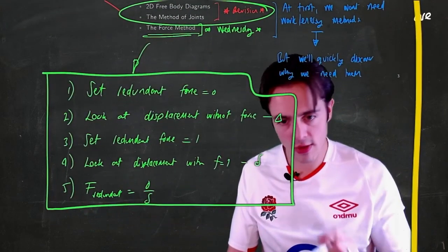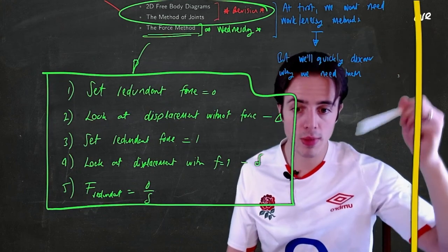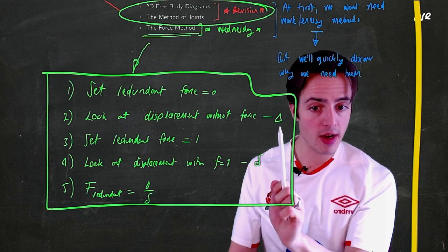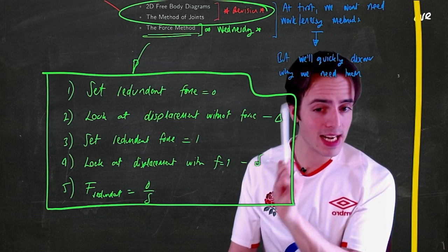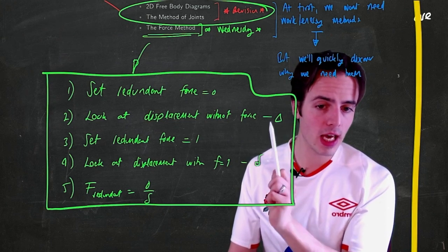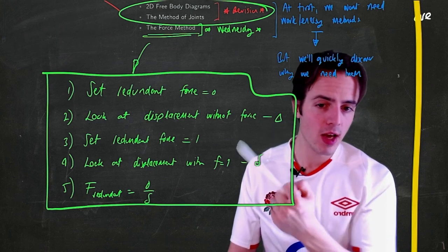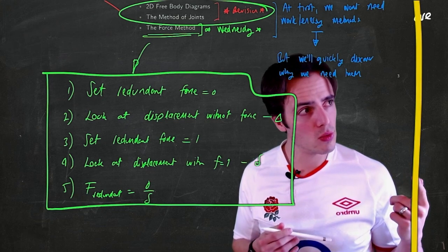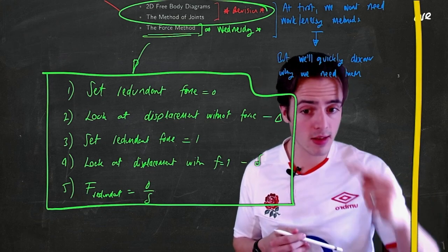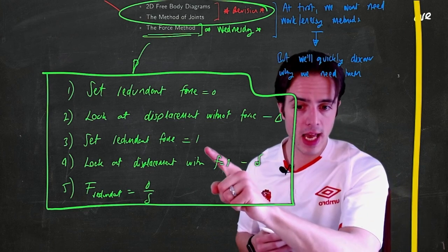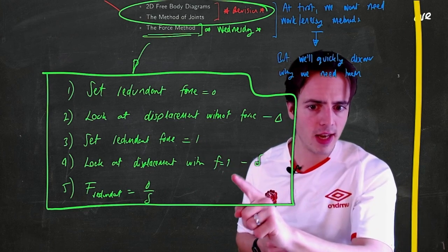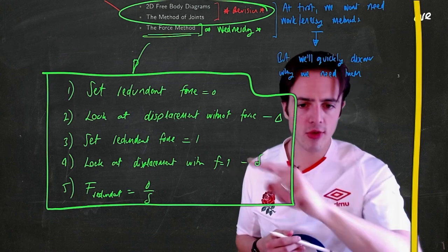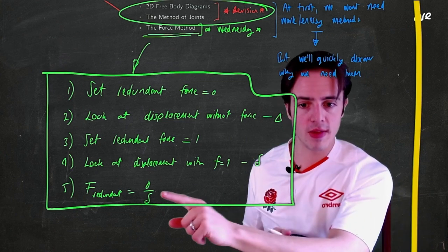The reason for that is you'll see that using the force method, which should not be new to you, we've got to analyze the system with no force there and determine a displacement. That's a lot of calculation, and in order to do that, using Work-Energy methods and the principle of virtual displacements, we actually have to solve the free body diagram once there, I think. Method of joints certainly twice just to get to this point. And here we've got to do the free body diagram again. And then here we've got to do the free body diagram and the method of joints, I think, twice again. So overall, we're doing this about 5 times to determine this bit that we care about.